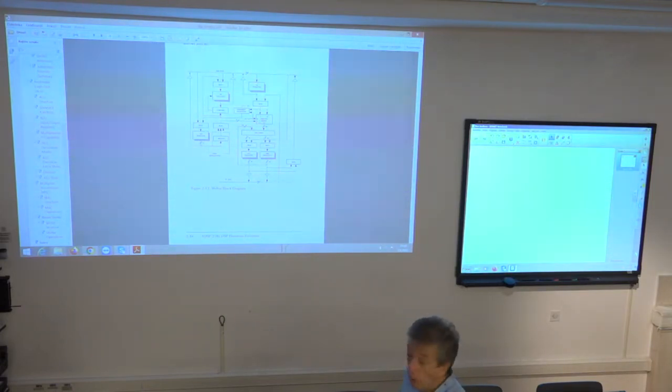But if you want to normalize the value, actually the direction is opposite of shifting. So with this instruction, you find out what is the exponent of the shifter input value, and once you have this exponent stored in the SE register, then you negate this value and use it to shift left the corresponding number of positions. So that is useful for the normalization instruction.